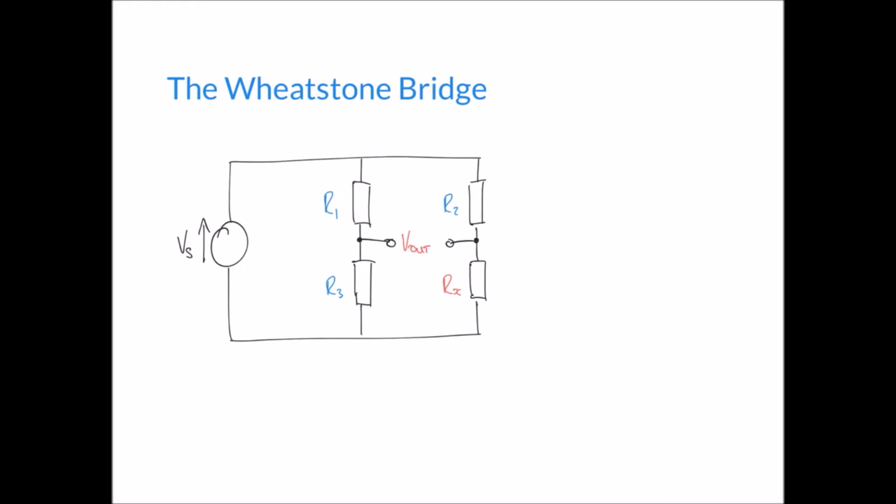One thing that we haven't mentioned so far is that for the Wheatstone Bridge circuit to work, and for us to be able to use it to determine the value of our unknown resistor Rx, one of our other resistors needs to be a variable resistor. And it doesn't actually matter which one. It could be R1, R2 or R3, but one of them needs to be a variable resistor. And so for our example, we'll make R2 a variable resistor, which is denoted by that diagonal arrow going through the resistor there.